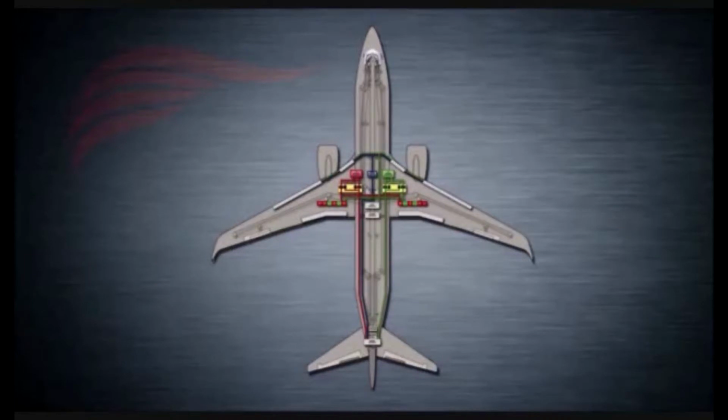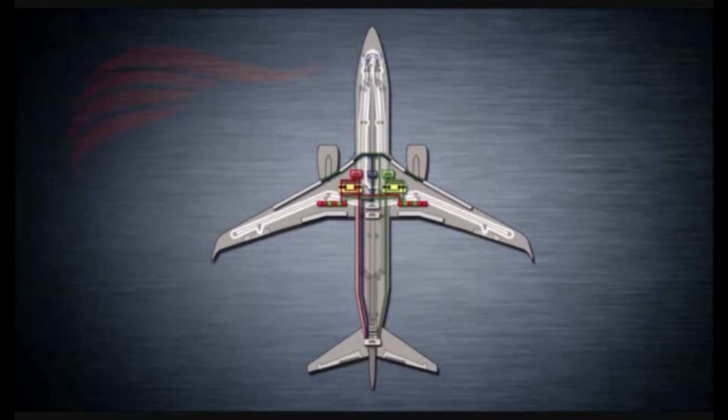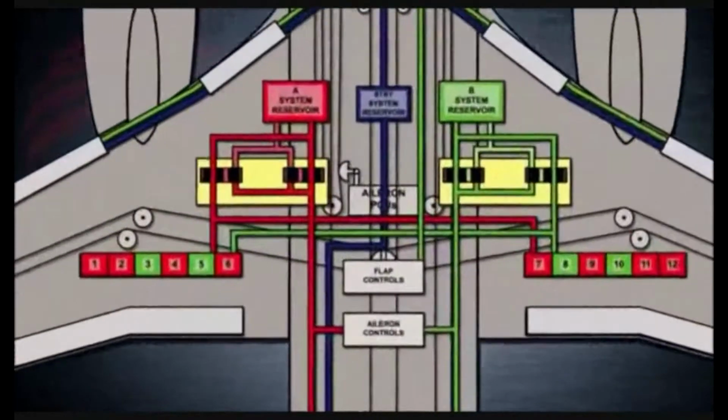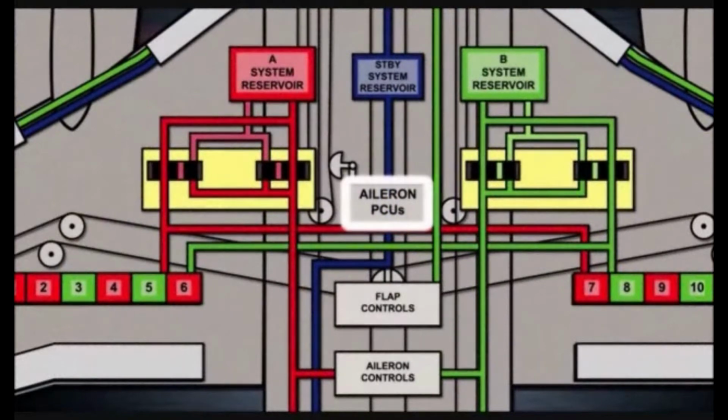During manual operation, the flight crew controls the roll attitude with control wheels that are interlinked mechanically in order to provide system redundancy. Just like with the elevators, the ailerons are actuated through pairs of cables that transmit force. Ailerons are also operated via the Aileron Power Control Unit, or PCU, that acts as an interface between the pilot's mechanical inputs and a series of hydraulic actuators that move the ailerons with wing cables.